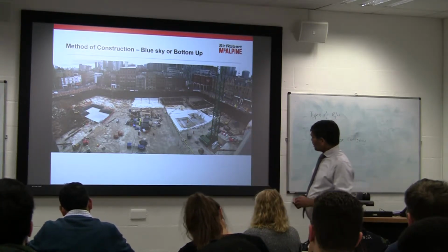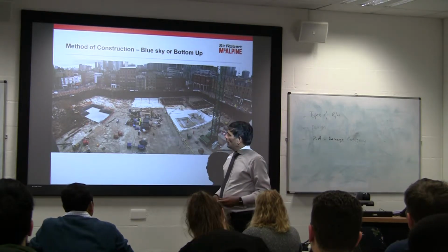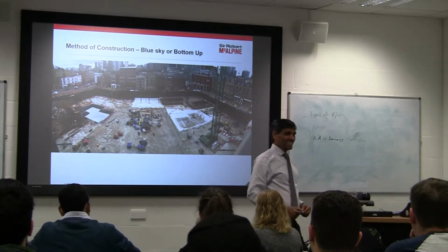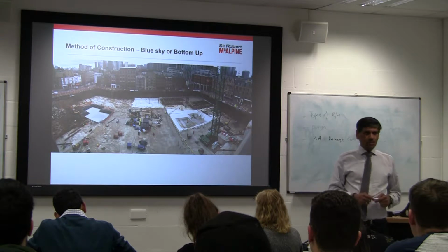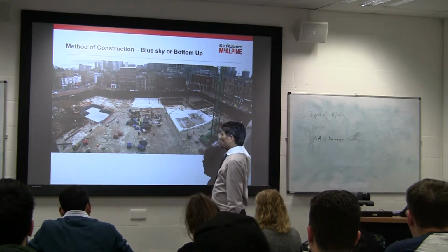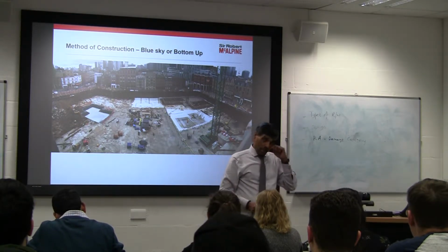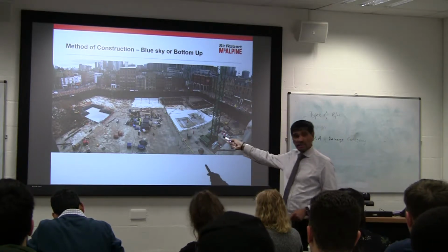One of the things with the blue sky option is obviously you've got to think, how long does it take to dig all of that volume? So here, the situation is that the time permits you to dig. If you imagine, as I said, these are roughly about 100 meters by 50 meters, so 5,000 times, let us say 10, including your bulking, we are talking about 50,000 meter cube of muck coming out from that site.